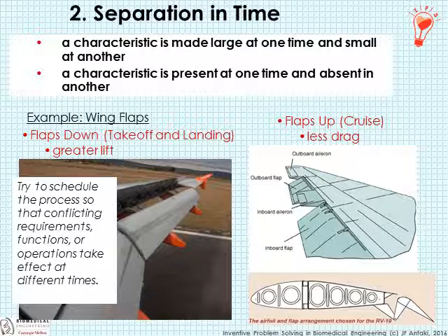We want there to be a great deal of lift, and we're willing to pay the price of additional drag. And this is where this sectioned airfoil comes into play, or the addition of flaps to an airplane wing. When cruising, we lift the flaps, we change the shape of the airfoil, and thereby achieve the optimal shape for that particular time during cruising.